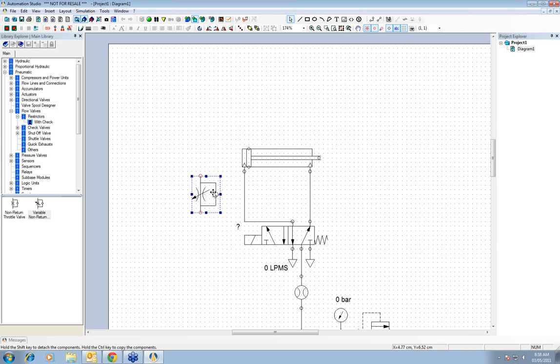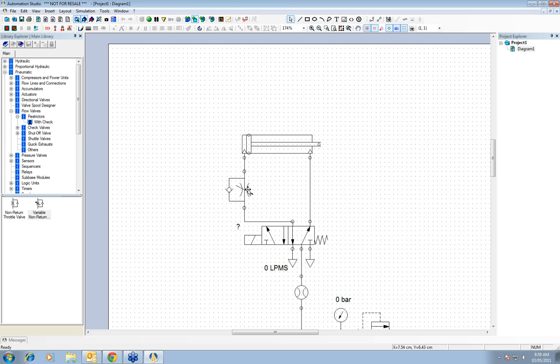So before you actually insert the component on the line, I prefer using the component alone and then using those transformations right here, so left, right, flip here, etc. And then once the component is perfectly at the position that I want it, I simply have to take the component, hold down Shift, and take the component on the line. Then release the mouse and release Shift, and as you can see right now, the component is attached on my line.